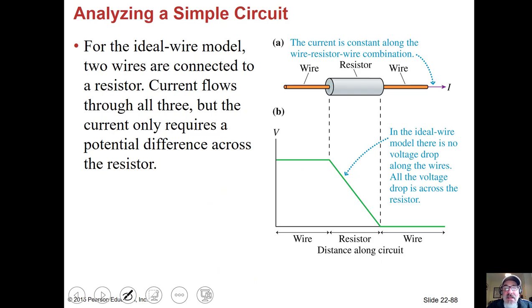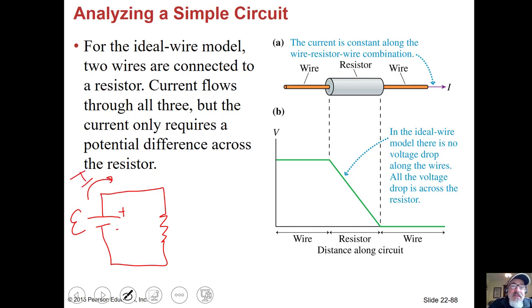So here's how the voltage is actually used. If you have a 10-volt battery, you're applying that 10 volts over the entire circuit that it's connected to. So current flows through all 3 elements: the wire, the resistance, and the other part of the wire. So the circuit might look something like this. This is the symbol for the battery. So we go through one wire, we go through a resistor, and then we go back to the other side. This is the positive side, negative side. And then we're pretending it's conventional flow, so current's going to flow like this.